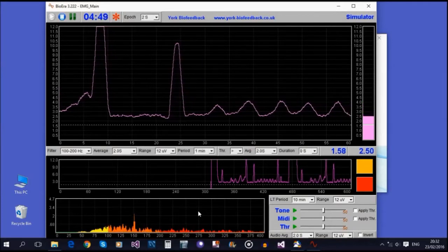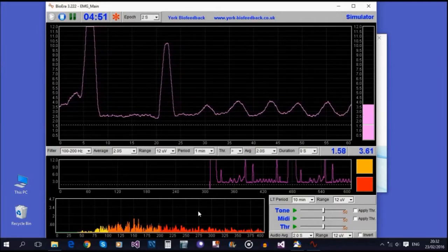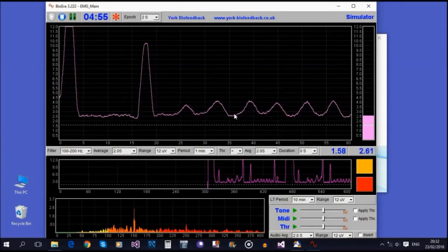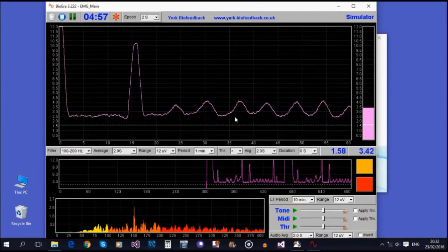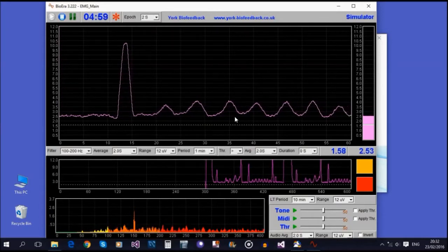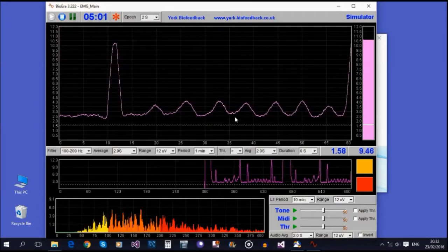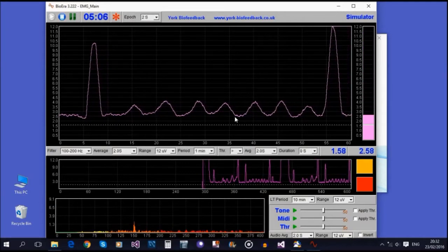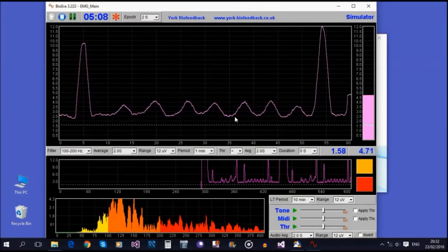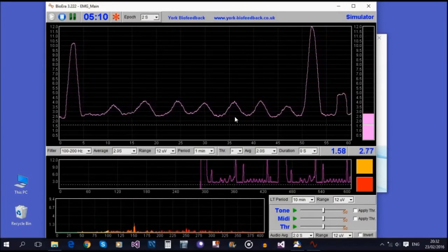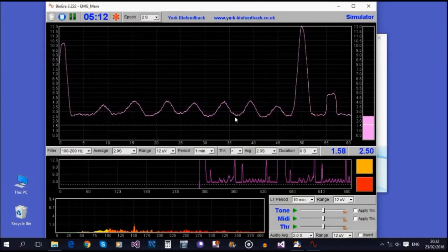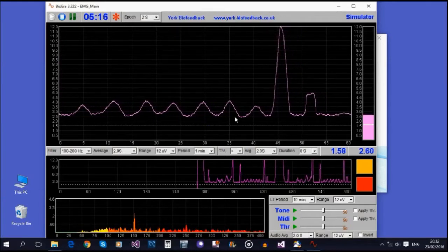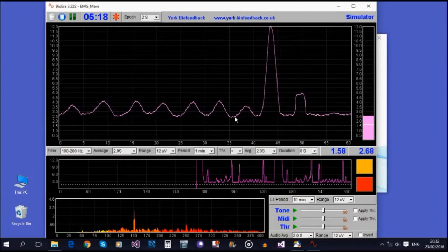That's based on the idea that the raw measurement of EMG is not quite like it is as you see here, but it's actually a rapidly oscillating signal. It's going up and down very, very rapidly, and the frequency of the oscillations is constantly changing. Or another way to say that is that there's not just one frequency, but a whole mixture of frequencies of oscillation, all wrapped up together in the same signal.